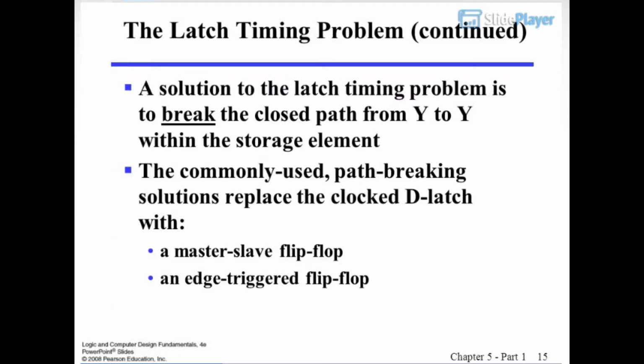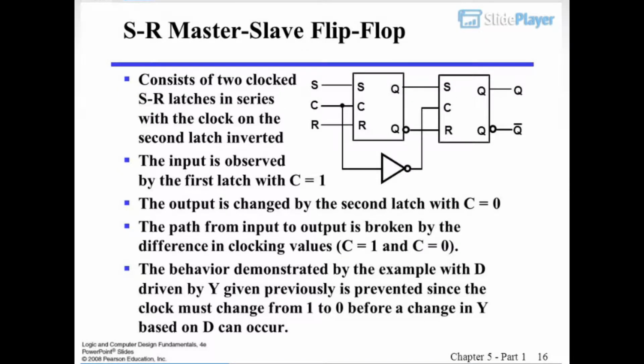The latch timing problem, continued. A solution to the latch timing problem is to break the closed path from Y to Y within the storage element. The commonly used path-breaking solutions replace the clocked D latch with a master-slave flip-flop or an edge-triggered flip-flop. Master-slave flip-flop.